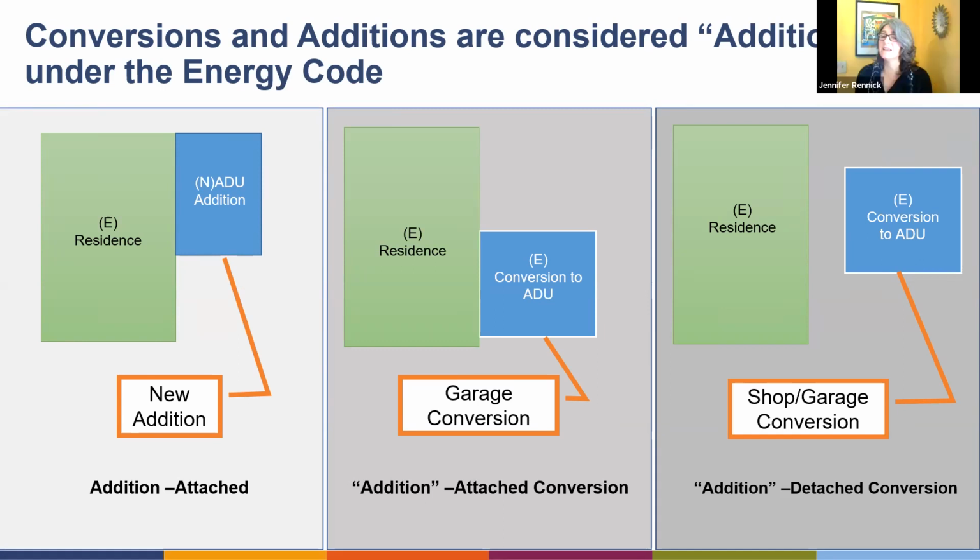Okay. Yeah. So I'm just trying to find options for the client. The client's not interested right now in seeing the split systems, the fan units on the interior. And I'm not sure that they'll want the ducted, because there is a ducted split system as well, correct? Yeah, and you can also do a ductless recessed ceiling cassette. It has 4-way throw or 3-way throw, and it's ductless and it recesses into the ceiling.